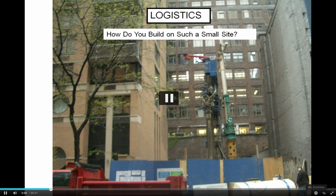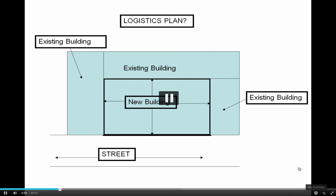So we're going to go through a lot of those, and this is a typical site here, between like a brownstone and another building. You've got this wonderful site that's going to come up with a 10-story apartment, but you know what, it's tight. And you got to work around it. So what you see there is a soil rig, probably drilling caissons in for foundations or piles. Looks like it's going to be some kind of pipe pile that they're going to work in over there, or maybe some kind of grout mix pile. So you have to work with what you've got. And with that, you start thinking of logistics.